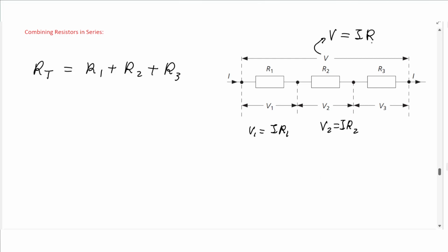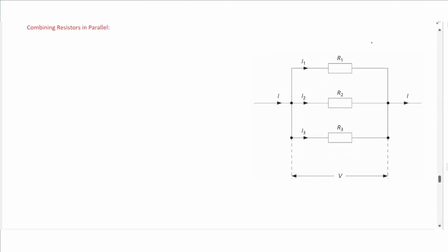You cannot use the whole voltage for all components because voltage is divided. You cannot use the total resistance for all components since you might have different resistors, and the total resistance is not the same as each individual resistance. In parallel, the voltage is the same, the current gets divided.